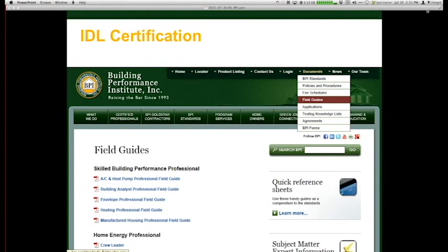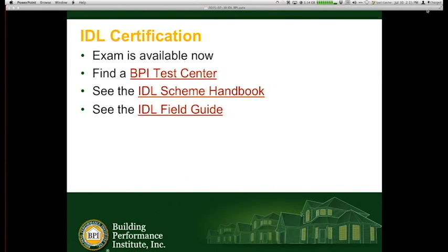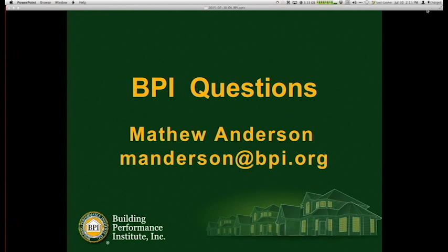All right. So, again, here's where you go forward. Your field guide is there. That's what we had, and these are things that are available out there. We've actually also given them to you. So there is no written exam. You are just going to demonstrate your ability to set up a duct tester and do a duct test, and also to do a leakage to outside test, which now includes a blower door, and also do a blower door test by itself.